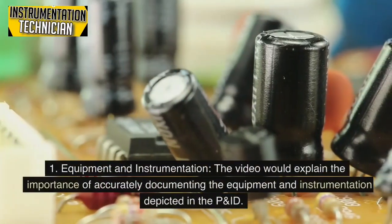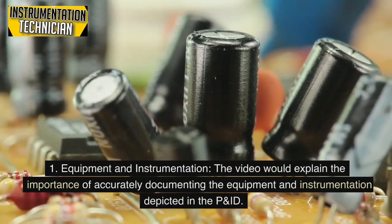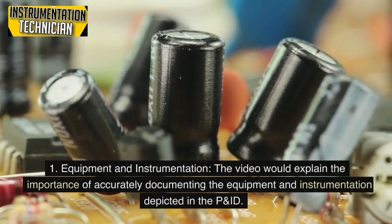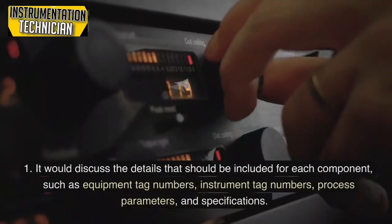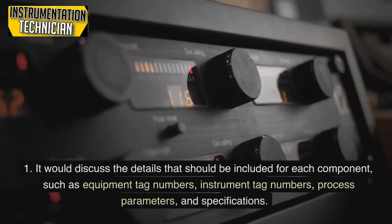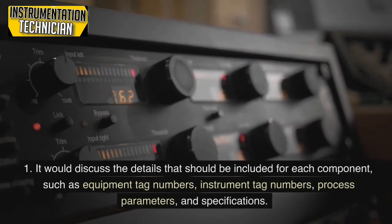1. Equipment and instrumentation. The video would explain the importance of accurately documenting the equipment and instrumentation depicted in the P&ID. It would discuss the details that should be included for each component, such as equipment tag numbers, instrument tag numbers, process parameters, and specifications.